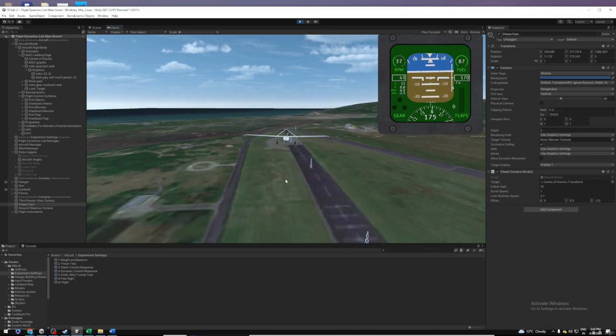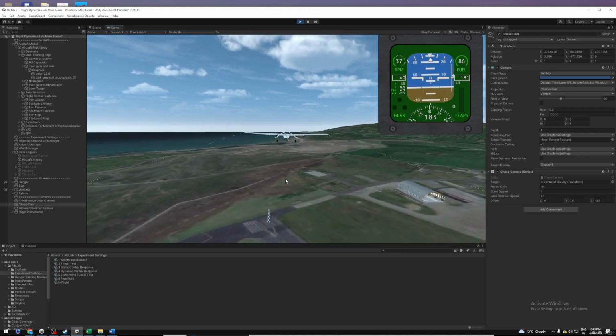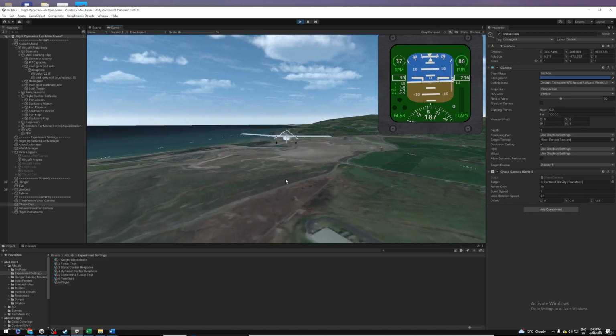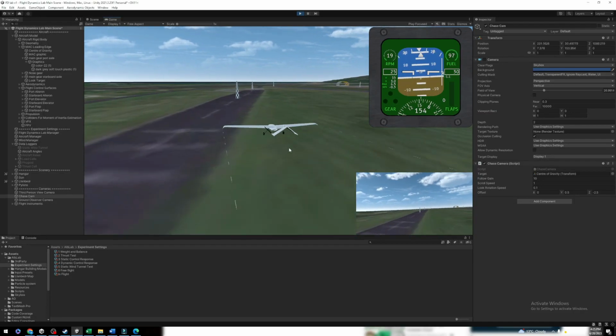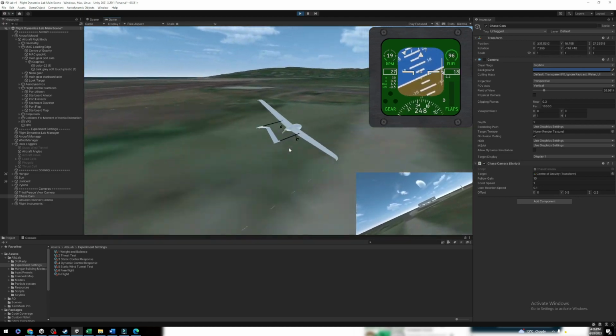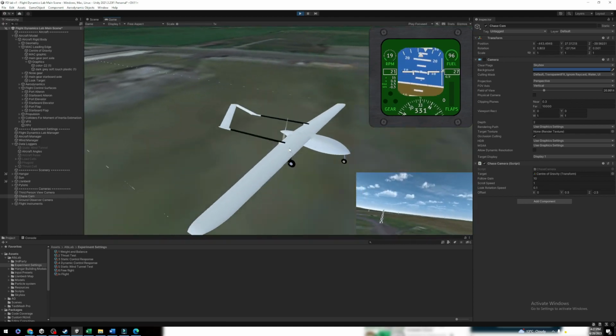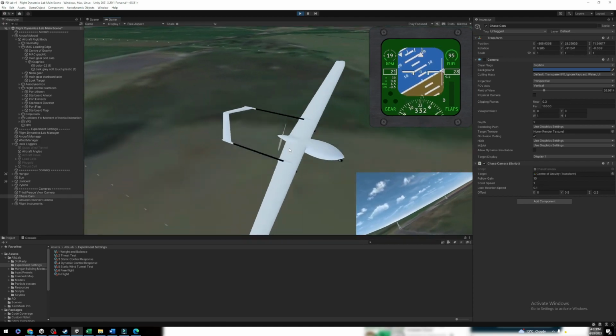This refers to the long period oscillation of an aircraft at a constant angle of attack, which typically leads to an uncontrollable spin. Finally, after achieving a trimmed and stable aircraft, we managed to free flight around the test course, aiming to maintain a speed of 20 meters per second at a target altitude of 30 meters. Thank you.